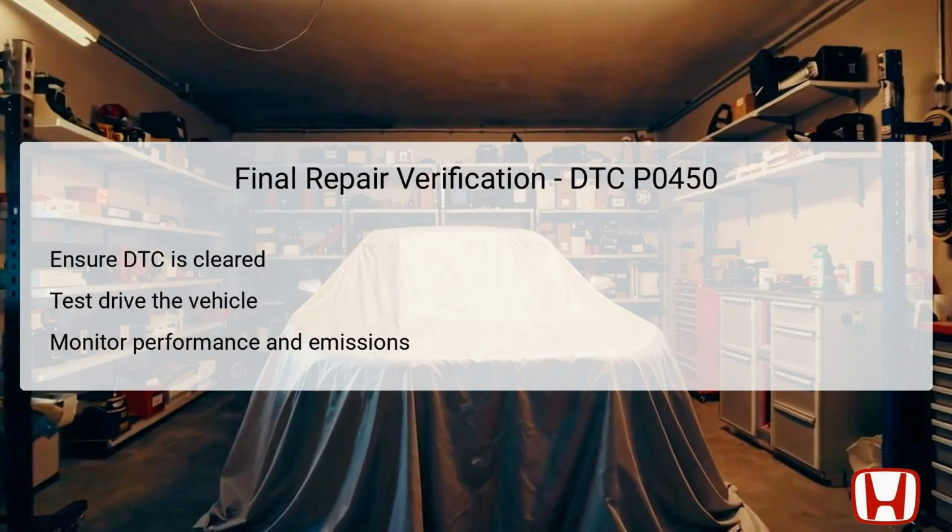To confirm a successful repair regarding DTC P0450, a final verification step is essential. After completing any necessary repairs, ensure that the DTC has been cleared from the vehicle's memory using the HDS. Following this, conduct a test drive to assess the vehicle's performance under standard operating conditions. During the drive, monitor engine behavior, fuel efficiency, and emissions to ensure everything operates as expected.